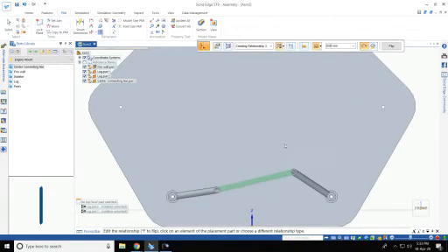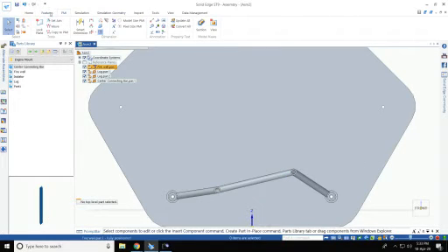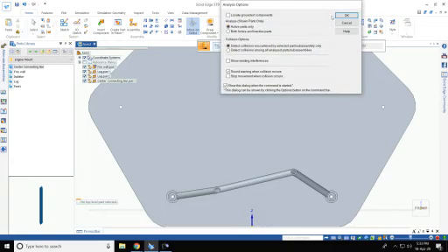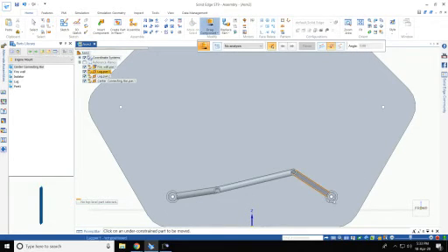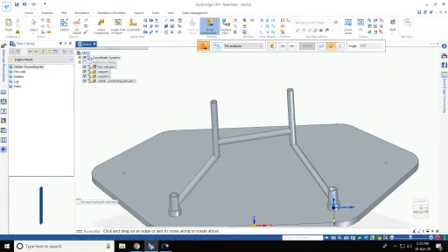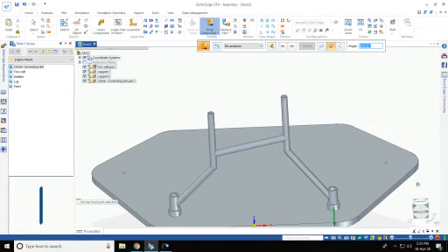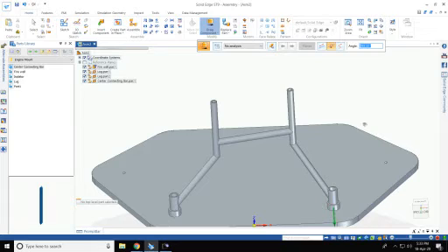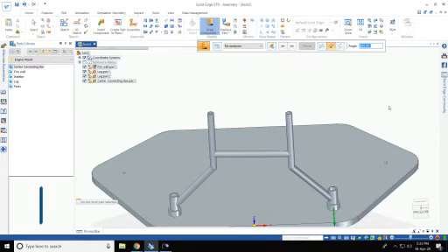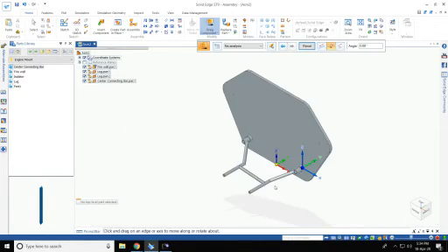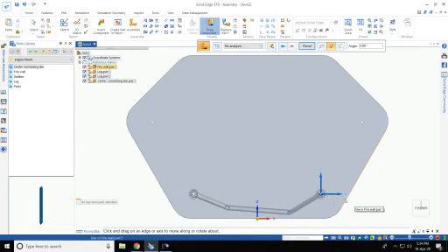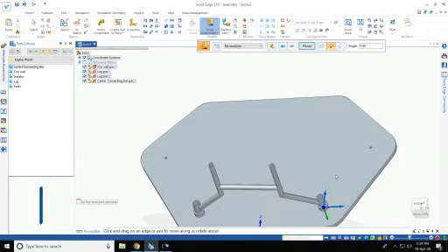So let's say it didn't quite set correctly, but if you're able to move it, go to home, drag this component on its y-axis. Yeah, the mobility is still there. Okay, this is how you want it. So that will sit on its own when you connect the next relation.